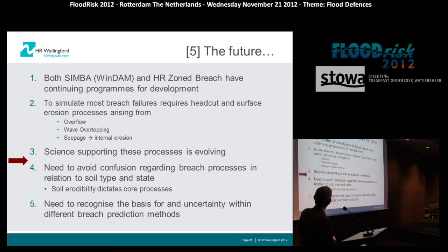There is a need to avoid confusion regarding breach models and soil types. There are a lot of models presented ignoring the type of soil that they've been based on, whether it's head cut, whether it's surface erosion, and so on. There is a need to recognise that breach models are uncertain. There is no right answer.